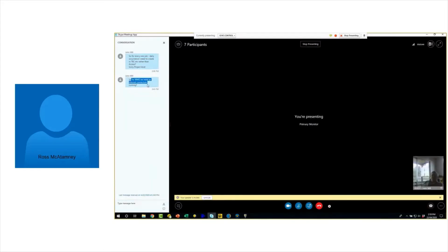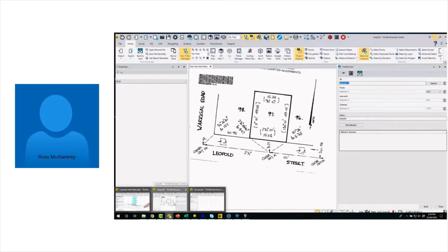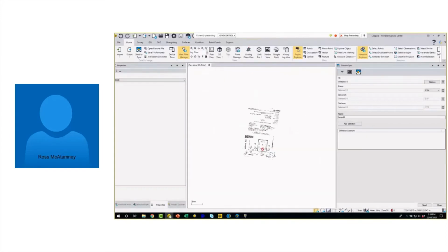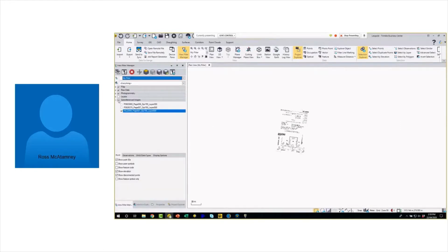So for web map services, John, yes, we do need internet connection running for web map service. If you're in areas that don't have a web map service, don't have internet coverage, or it's not the workflow that you would primarily use to have a SIM card in the controller, then what I would recommend is what I was discussing this morning with Trimble Business Center and Trimble Access working together.